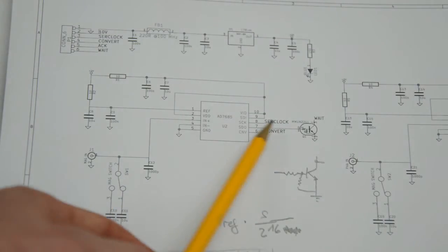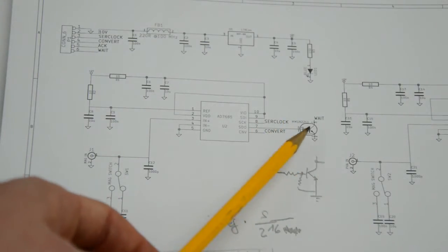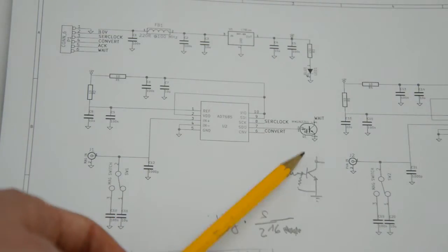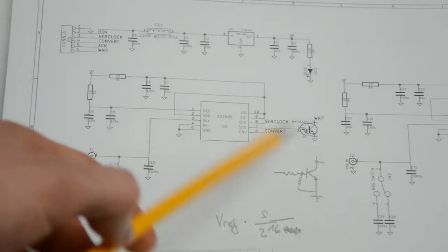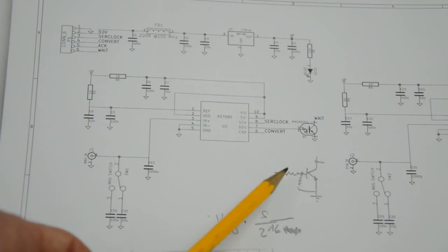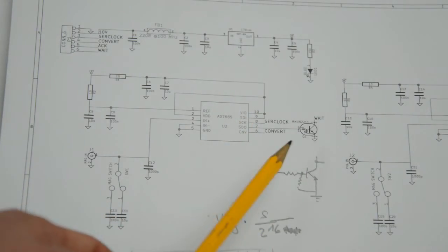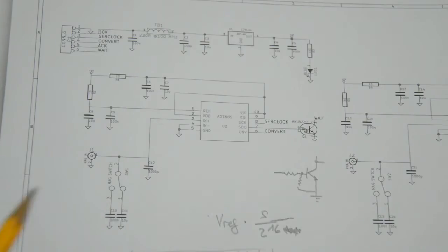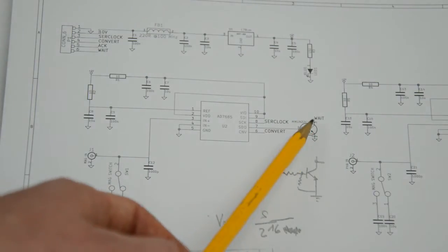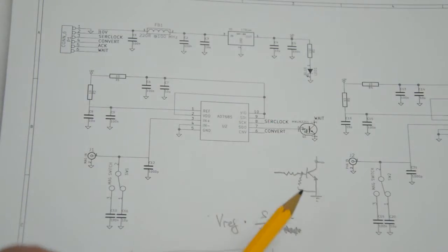through this SDO pin here, that is then connected to a transistor that is a pre-biased digital transistor. So there is nothing special to that. It's just that there are internal bias resistors. I redrew this here. You can see that there is a base resistor and also a pull down on the base. If memory serves, these are both 1K. So that just doesn't need external resistors, but other than that, it's a pretty ordinary transistor. And this collector here is then pulled up by the internal pull-up of the PC, and that's how you get your measurement back into the PC.